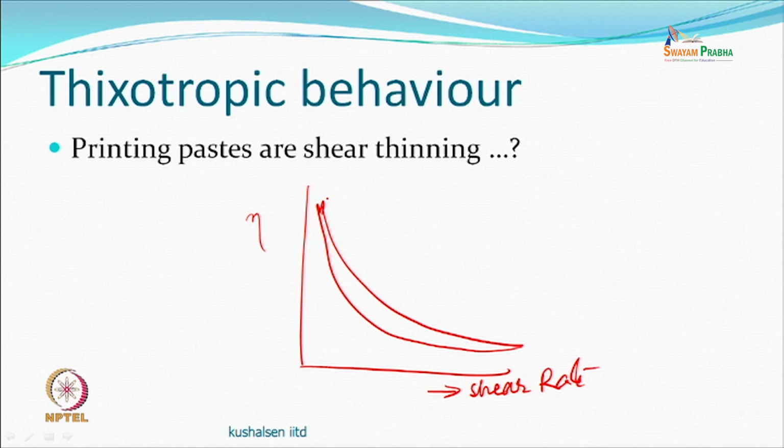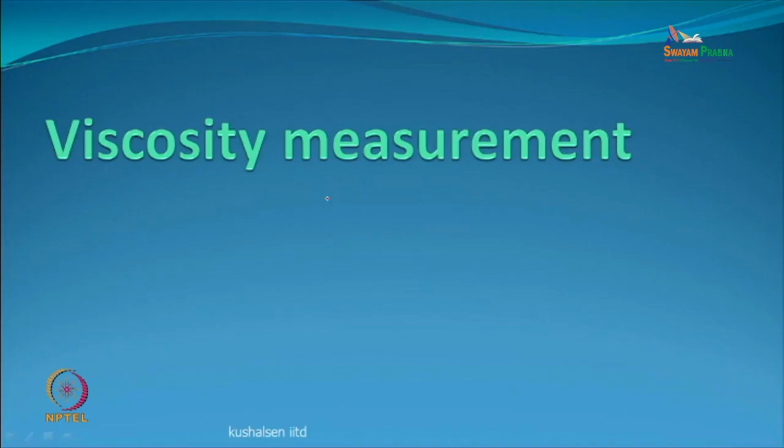But this sensitivity applies to every type of polymer that we would require for printing. This is not pH dependent, although we all understand viscosity is temperature dependent. So if you increase the temperature, then things will be different. So whenever you measure, you will have to say at what temperature did you measure. Not only that, people will like to know how did you measure.